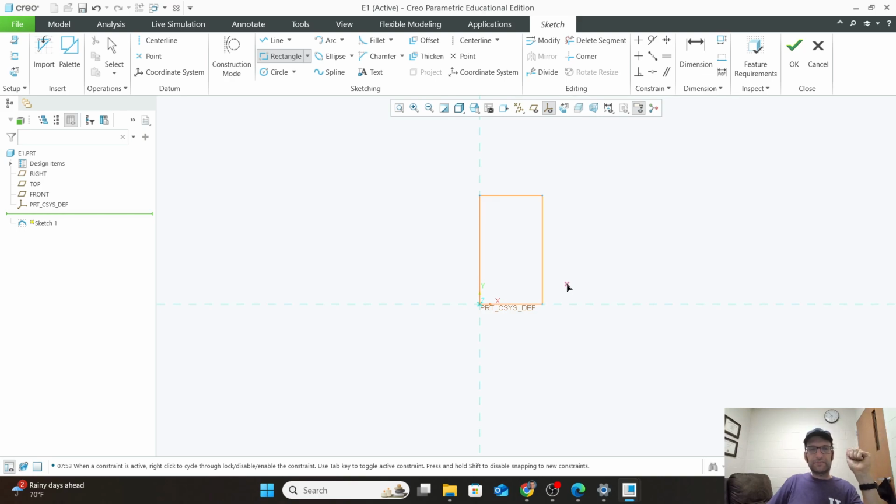When we're drawing something, when we're creating something here, we really want to get close at first. And then through the use of constraints, which are things that help us lock certain elements and aspects of that design in place, and dimensions, we're going to refine what we want. So if we know that we want a particular dimension on something, like a 3-inch by 5-inch, we're going to set that in there. So let's go ahead and do that 3 by 5. But how do we do that?